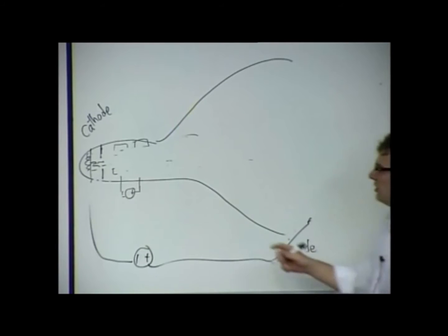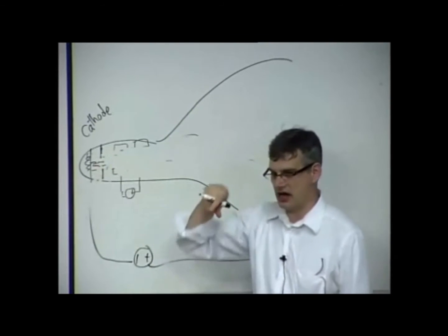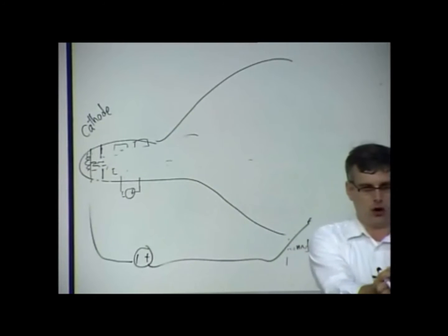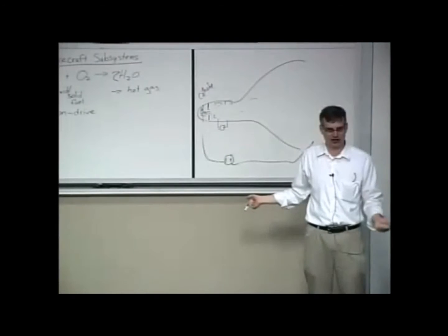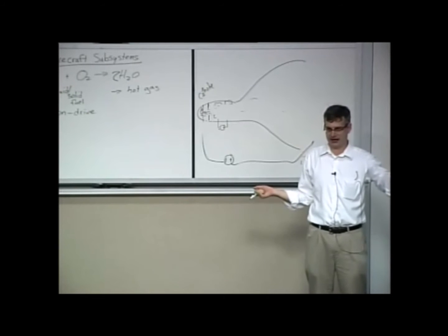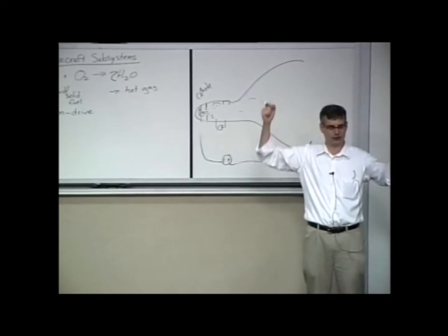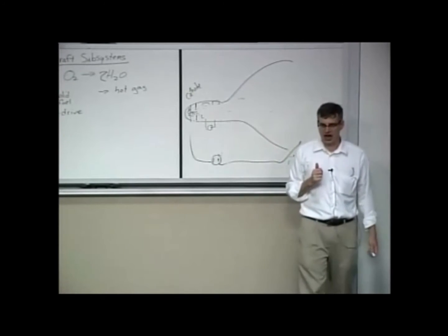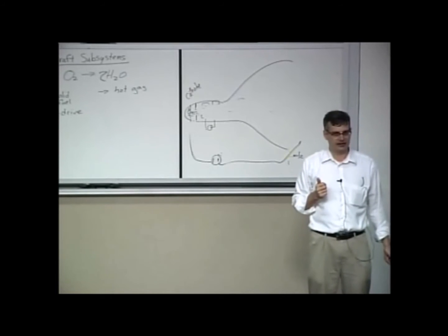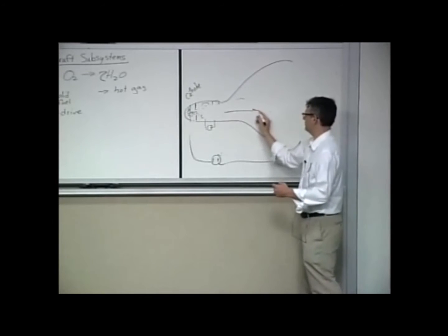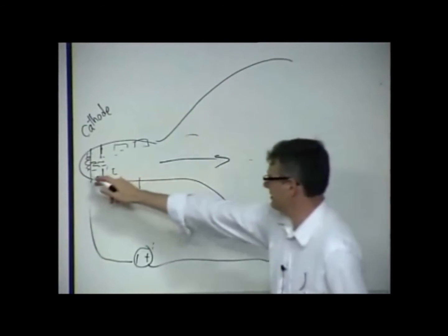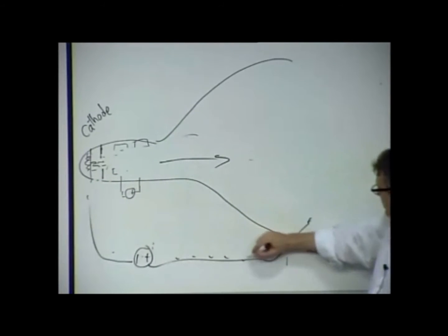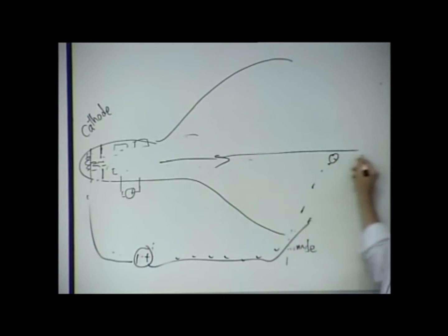Now, what is an ion drive? You take a source of ions, a propellant of sorts. You heat it up and you rip off some of its electrons. So now you have a heavy positive ion and some electrons that are kind of floating around. And if you've reversed the polarity, you're going to accelerate the ions in a particular direction out this way. And then you're going to complete the circuit by letting the electrons jump back into the ions as they're accelerated out in the electrostatic field here.